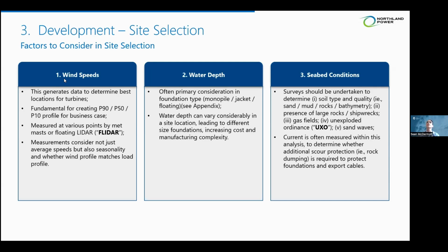So the projects that are pursuing anything beyond 80 to 100 meters tend to be floating projects, and floating can go to much deeper waters. But a big part of determining where you want to be is the water depth. As a general rule, the shallower the water, the cheaper the foundation, which helps improve your capital expenditures.